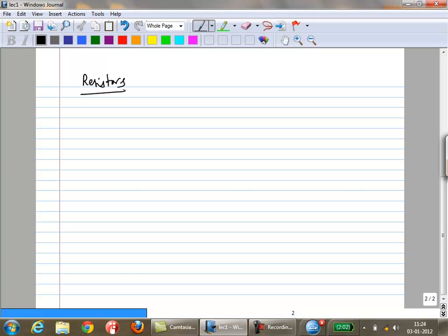How about resistors? So we looked at the MOSFET. Okay. Next type of device is the resistor. So you actually have several kinds of resistors. You have polysilicon, which is usually the material which makes up the gate of the transistor. And then you have several kinds of diffusion resistors.